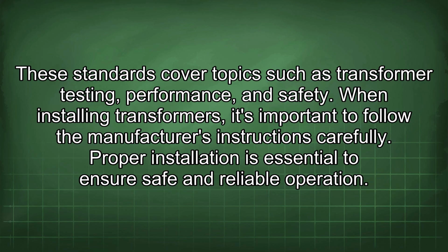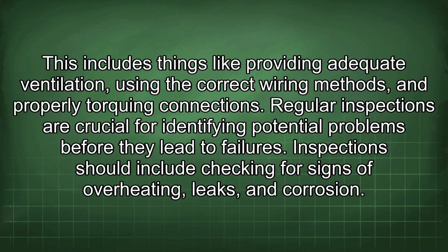When installing transformers, it's important to follow the manufacturer's instructions carefully. Proper installation is essential to ensure safe and reliable operation. This includes things like providing adequate ventilation, using the correct wiring methods, and properly torquing connections.